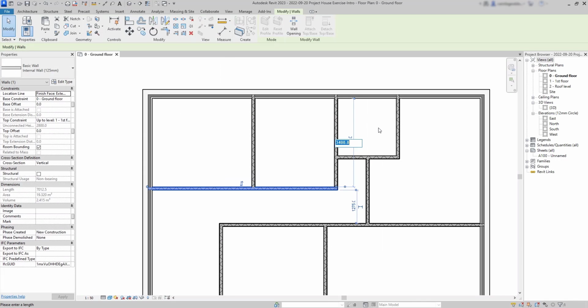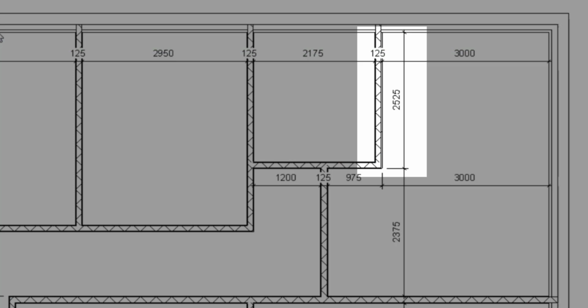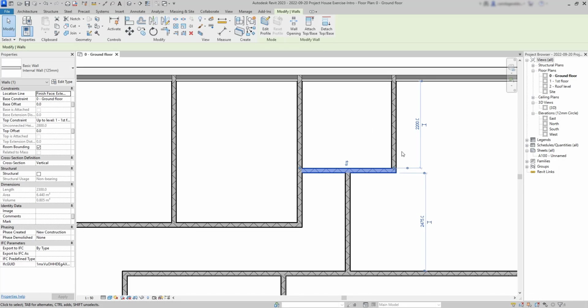Back in our drawing, I'm going to edit this dimension to 3575. And for this wall, I need something different. The length of this temporary dimension is measured by two different points if we compare with the PDF file. But this is simple to solve. I can click on this grip at the baseline and drag it to the other wall face. Release now the button because it's snapping to the face. Then I can change to the length that I need.